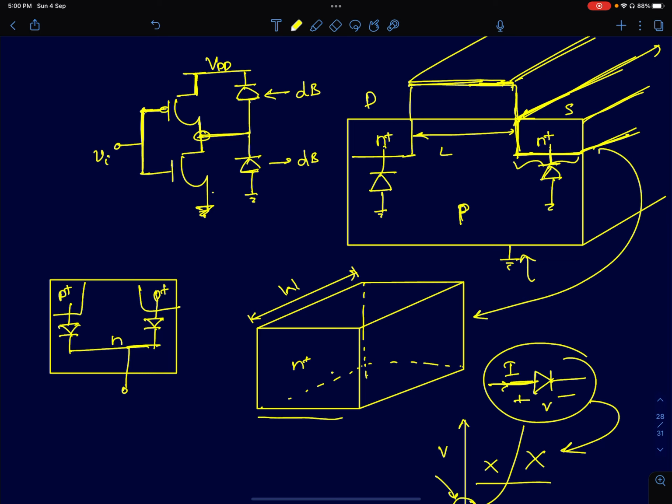Okay, so let's call this dimension T. The area of cross section of this diode will depend upon the device width and also the width here. And there are techniques to estimate this diode's capacitance very accurately using some simple geometric approximations. Most courses on basic digital VLSI design would cover that. Most textbooks have that. So you have a PN junction diode forming this way, on this side. So on all the faces of this MOS device except the top face, and if the channel is conducting, you ignore the other face as well. And on all the other faces, you'll end up getting a diode structure.